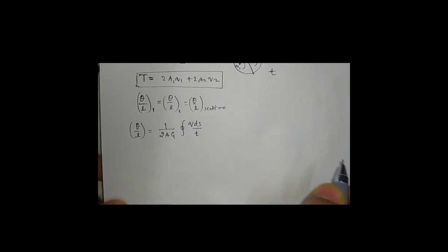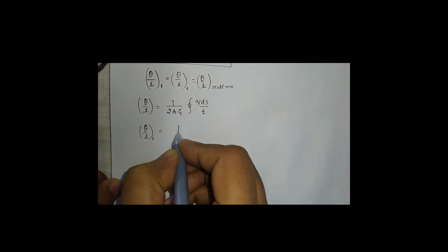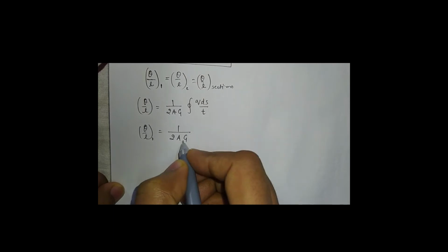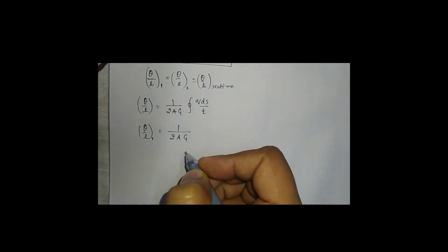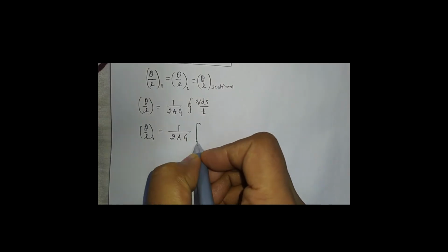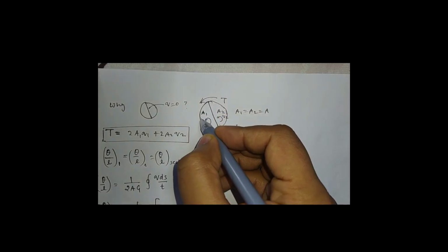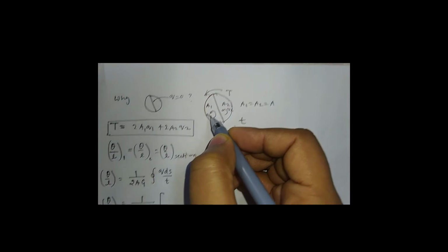Now we are considering cell 1. Then for cell 2, area is same. We are also assuming the shear modulus is same as nothing is given in the question. So for cell 1, the shear flow in this outer ring is Q1.